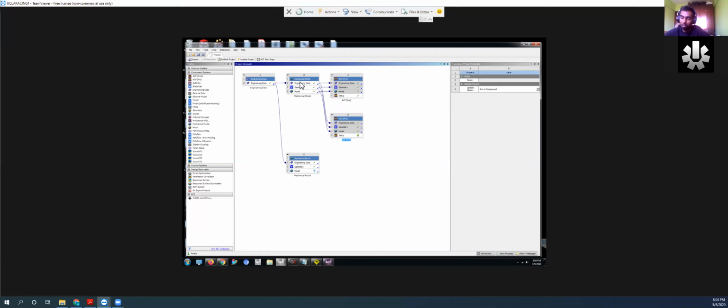I like to do this when I'm trying to cut down on the number of plies I'm using. So I will say, okay, I know this is the base that I like, but I want to see whether I can further cut down on a few more plies. Then I'll start copying over the mechanical model stuff into different ACP Pre's and playing with it there, so that you don't have to adjust the data that you already created for your base model. It's just nicer that way.